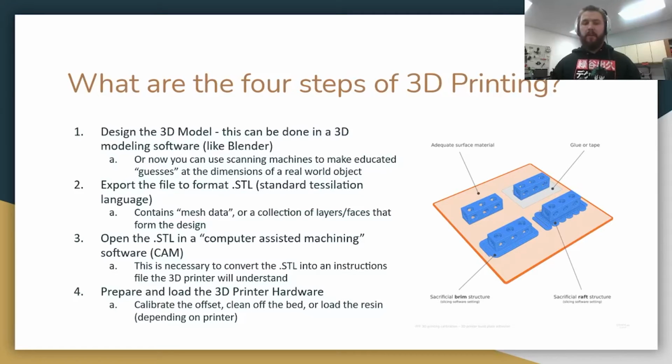called slicing. So once you render it through the software and you've reviewed how the design is going to look before it's 3D printed, because really nice slicers will even show you where the nozzle will travel as it goes through the printing process, and you can see exactly where supports are, which is the structure that is in this image here. It's called a brim support structure, where they print layers of filament around the block so that the edges don't curl up from cooling too fast. That's more secure to the bed as well.